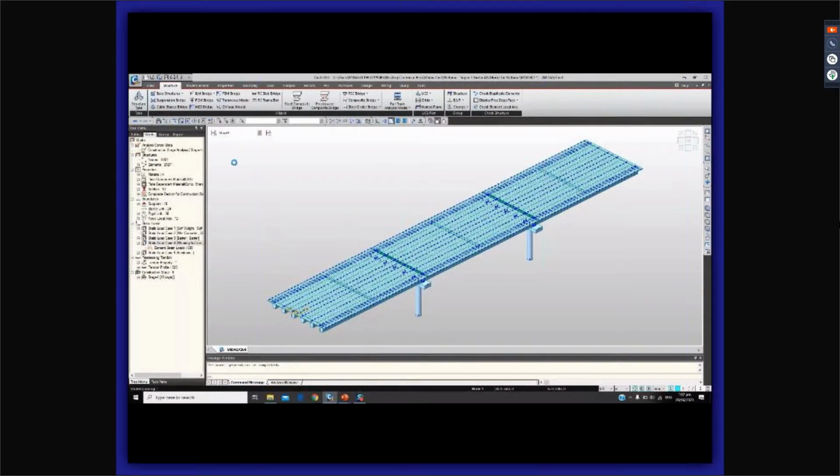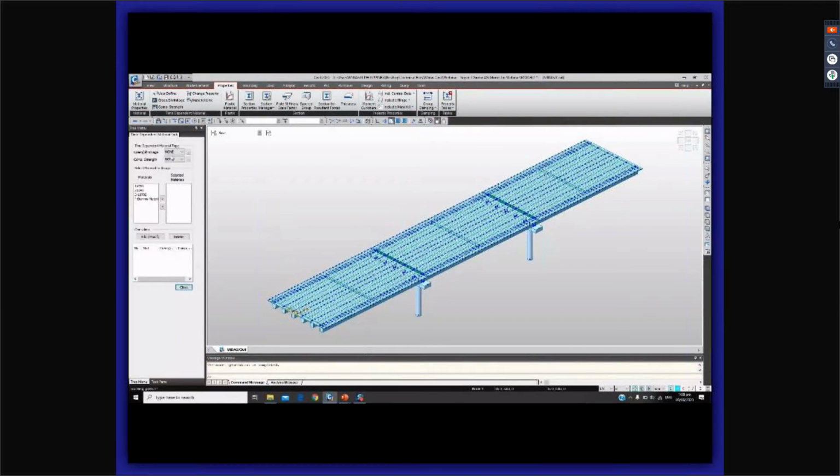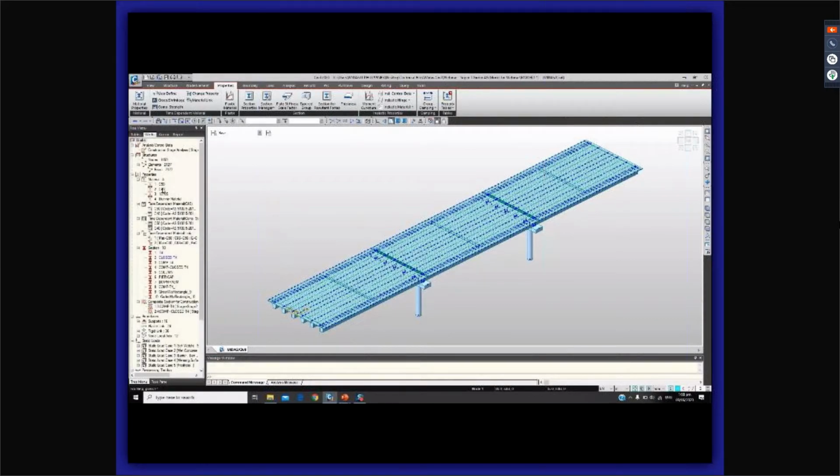And for stage 5, this is where the time-dependent materials are being acted on. So we can only make changes on the base stage of our model. So we need to just modify some of the properties. Say, for example, the material link of C50 and then C40. In order for us to attribute the compressive strength, creep, and shrinkage to C50, we can use the material link here. C50 and then which material for C40 as well. And then add. Now it is already assigned.